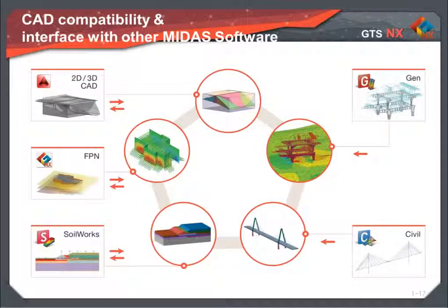and effort. Once the geometry is imported, there is a variety of different tools to fix geometric shapes. For example, where we have gaps between edges that should be connected, NX will remove these small surfaces and make the connections.